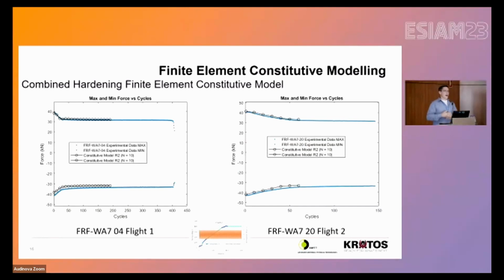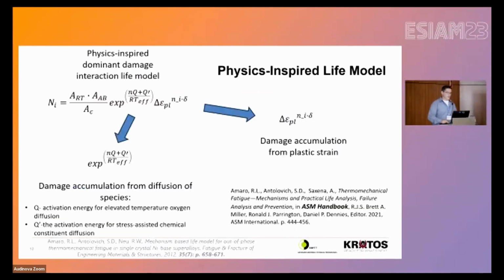And this is the Chaboche prediction of the stress relaxation within these specimens as a function of time. So in this particular case, what we're looking at is variable amplitude loading with varying temperature, and I'm predicting in the black dots the evolution of my material as a function of cycles. The actual material test data is in blue. You'll note I'm missing some mean stress evolution effects, though. The compressive side, I'm missing.